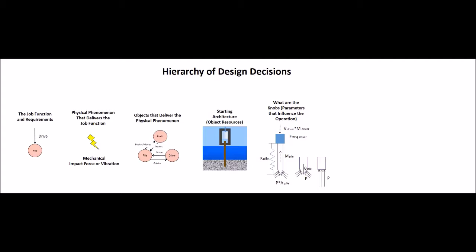Not all of the force or energy that goes into the top of the pile reaches the bottom of the pile. If the mass or weight of the pile is too high, a lot of the energy is used up in accelerating the pile itself. This is a lot like the trick where someone with a sledgehammer strikes a rock on somebody's stomach without causing harm.